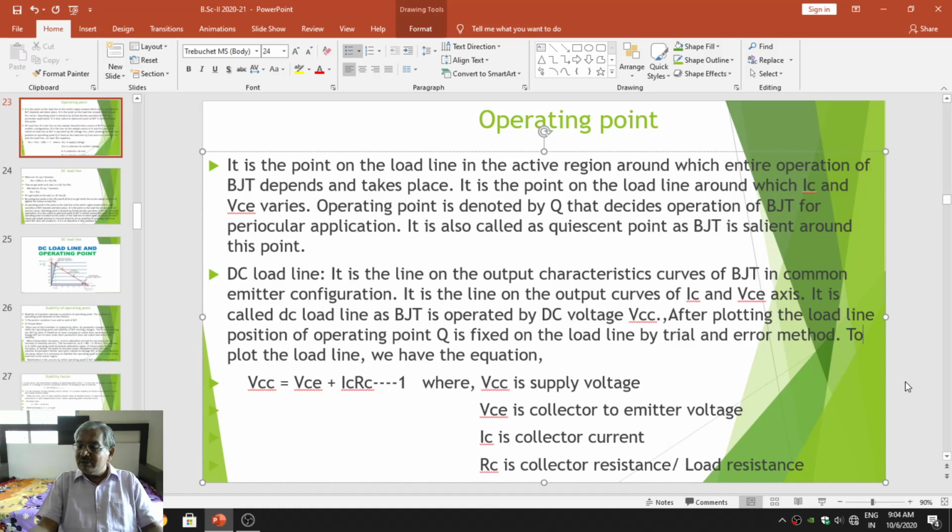in a proper region depending upon the purpose for which that transistor is being used, and that is whether it is going to be operated in the active region or in the saturation and cutoff region, to work as an amplifier or to work as a switch. For that particular purpose, we need the biasing,